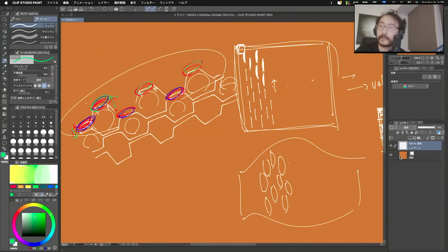Okay, I have a comment. Can I apply C++ knowledge to Houdini FX scenes? Only VEX. You could bring C++ knowledge, but maybe not C++, you could bring C knowledge, because you cannot create classes in VEX. So I think that's a big difference. It's pretty close to C, but it's not as sophisticated as C++. And you cannot use any external C++ libraries.